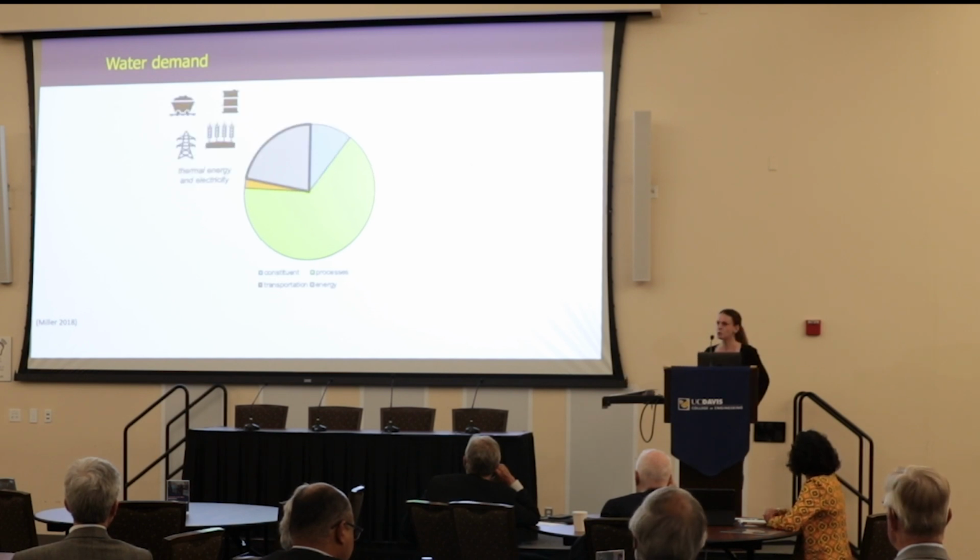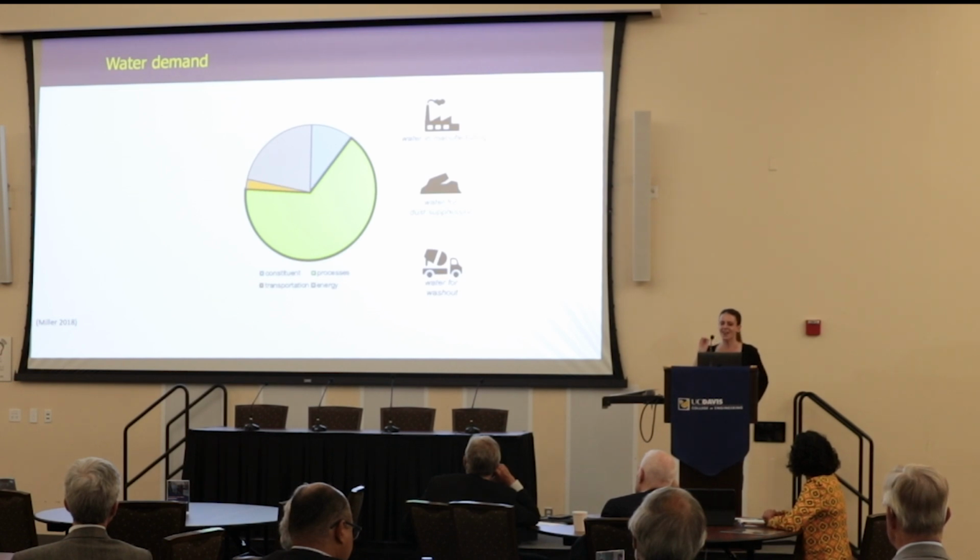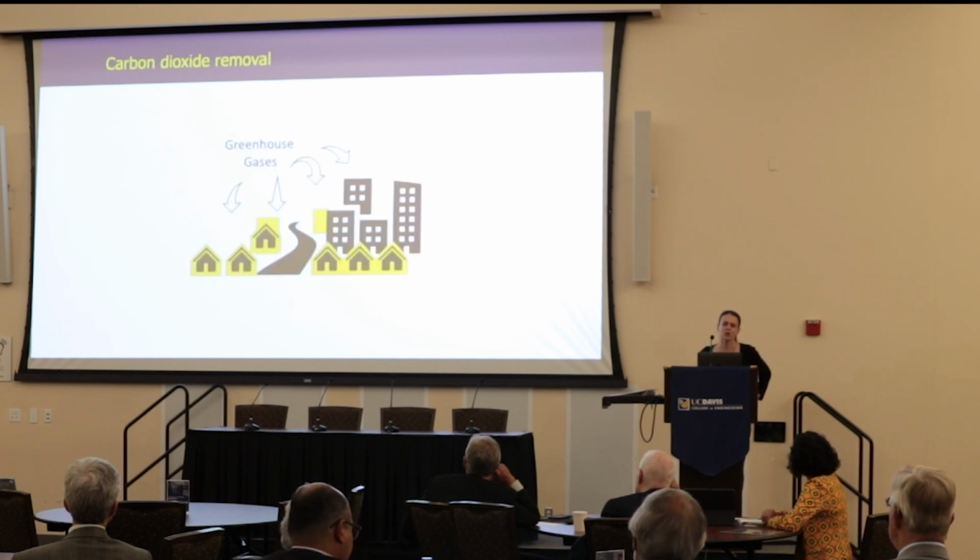But we have a huge amount that's tied to the energy to actually produce these materials, a wee bit that's actually tied to the energy resources for transportation, and then a lot that is tied to the processing. So this includes things like dust suppression, as well as factors like actually making sure that we have a washout for our concrete trucks. So actually making sure that we don't have concrete that gets stuck inside of those spinning trucks. So as we start to look at this, it could start to appear as an enormous challenge,